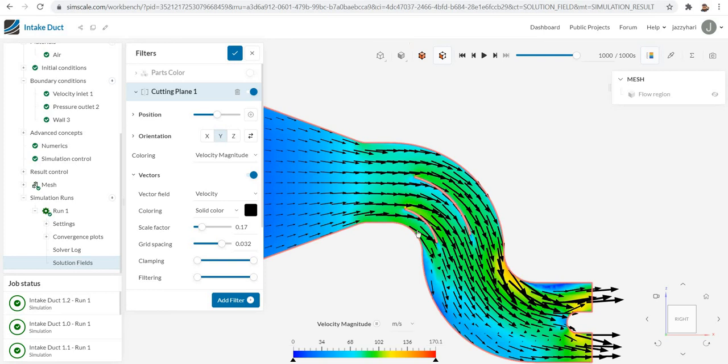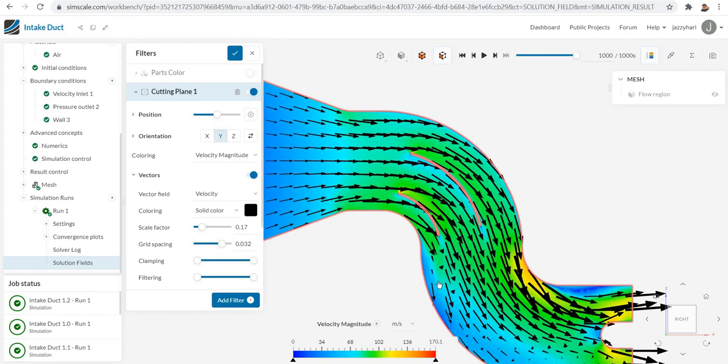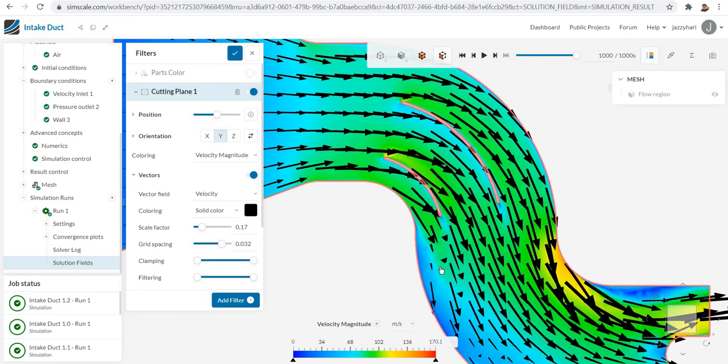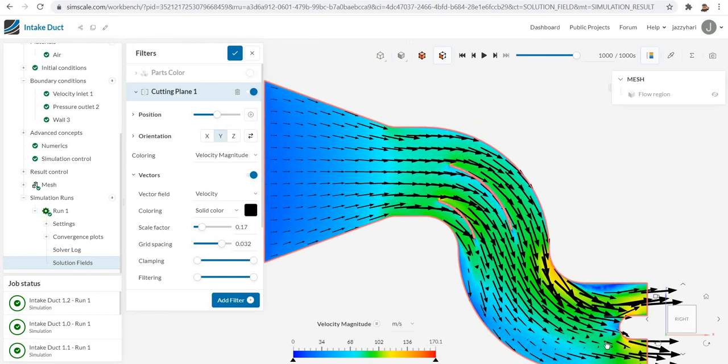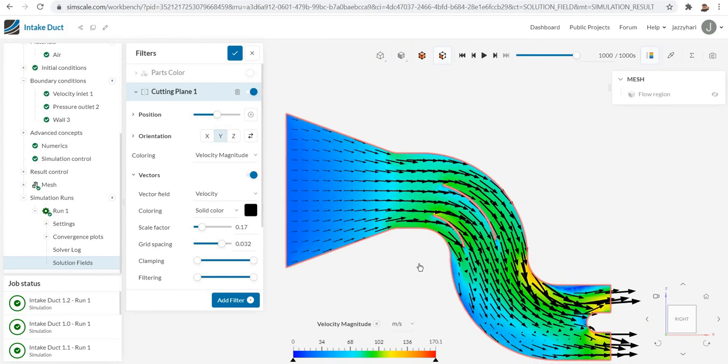When we put these two vanes, it improved the performance, and the losses are reduced. In the outlet area also, the flow becomes smooth, and there are no recirculations. Most arrows are going downward, there is no flow circulation. You can see there are no recirculations. So the energy losses will be very less in this final modification.